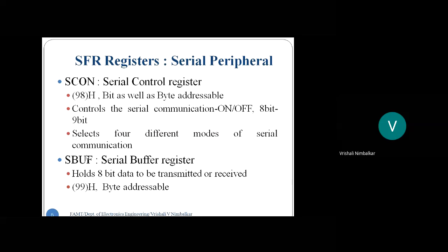For the user, it appears as if they are using only one SBUF. Internally, it is managed by the microcontroller which SBUF is to be used. So the user will have only one SFR address and only one SBUF register. But physically, internally, two SBUF registers are available.